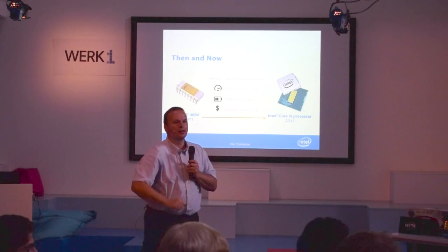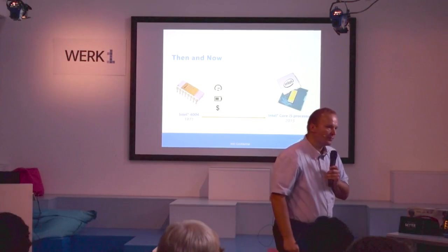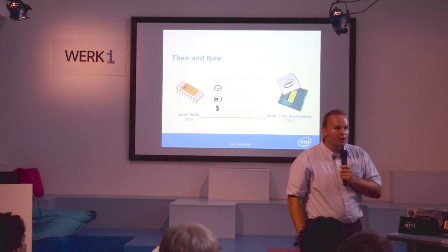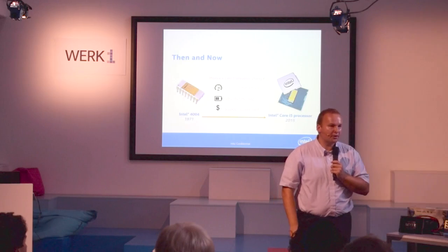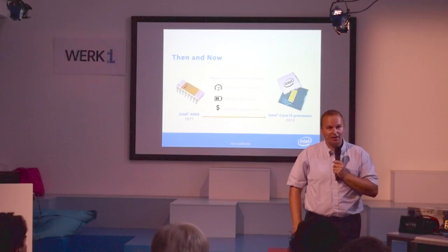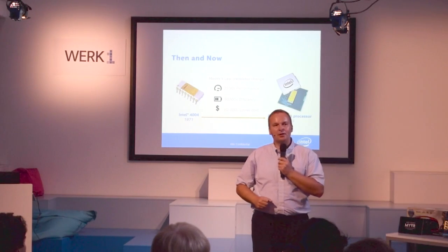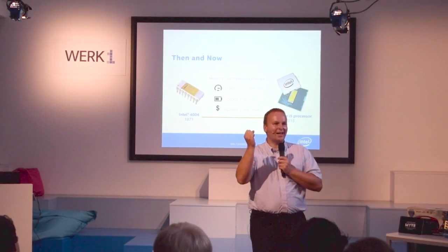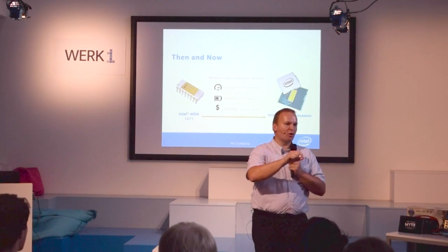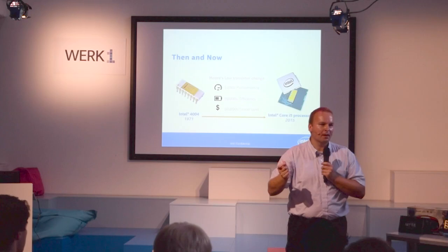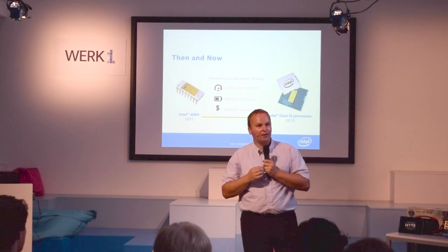You had one, right? You said you use UV light. So what's the current lithography wavelength you use? So the lithography we're using is 193 nanometer. It's not extreme ultraviolet yet. We would love to use extreme ultraviolet exactly for that reason I explained in the beginning, because that would shrink the writing pen significantly, to a pen that is smaller than the lines we need to draw. Unfortunately, extreme ultraviolet light is not powerful enough yet.